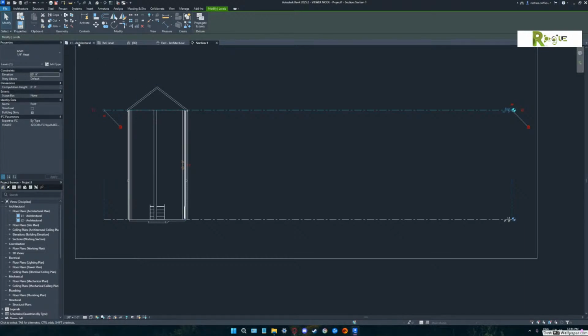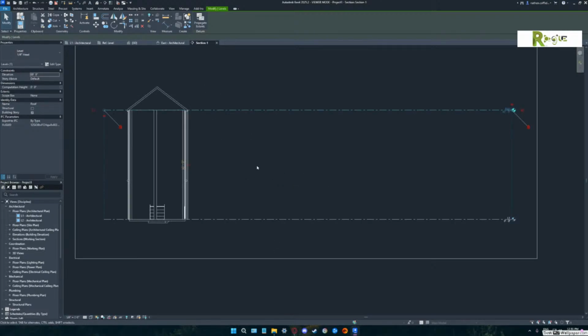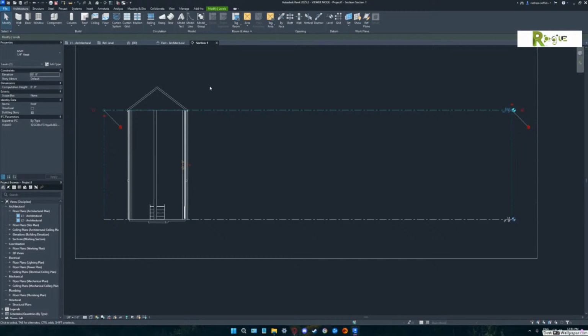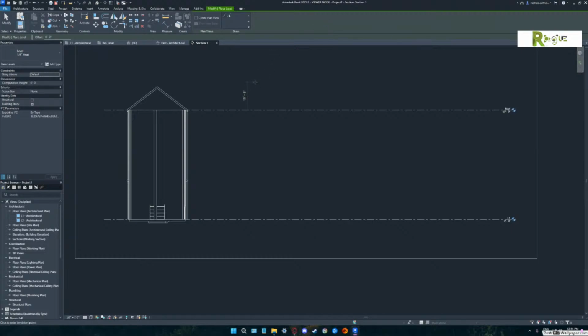the architecture tab. Nope, I'm sorry. Keep yourself in that section. The architectural tab. When I say that, I'm talking about the up at the very top. Oh, okay. Yeah. All right. So what we would see is at the very far right, not the last 4, but the 2 beside it, they say datum. You could add levels in here. Okay, this is what I was asking you at the very beginning. Yep. Now, you can either add levels or you can copy the level you already have.